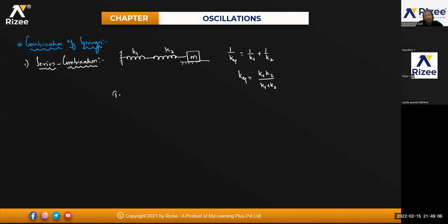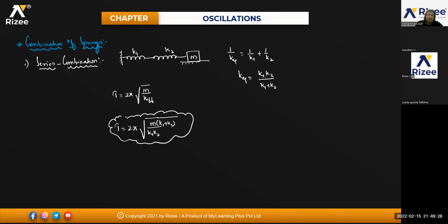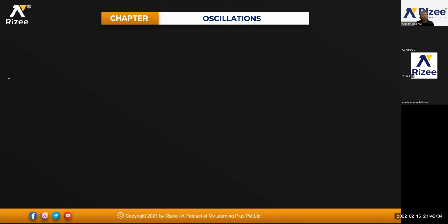And time period T equals 2 pi under root of M by K effective, where K effective equals K1 into K2 divided by K1 plus K2. So this will be the time period: T equals 2 pi under root of M into (K1 plus K2) divided by K1 into K2. Next, the springs in parallel combination.